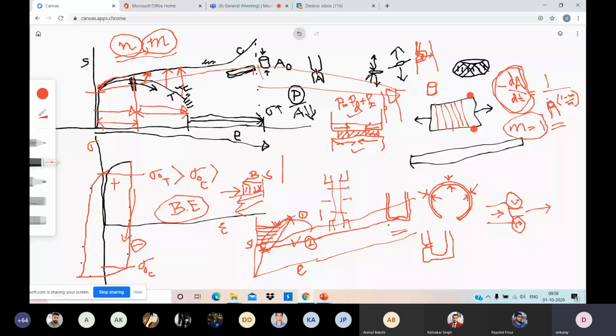You have to apply 501, 502, 510. But there is a risk that the metal continuously flows and fails under that load. That risk is not there in curve number 1. There you can apply a stress higher than yield stress, but you know it is lower than UTS, so no way it will lead to failure. Is it okay? Could you understand my point?